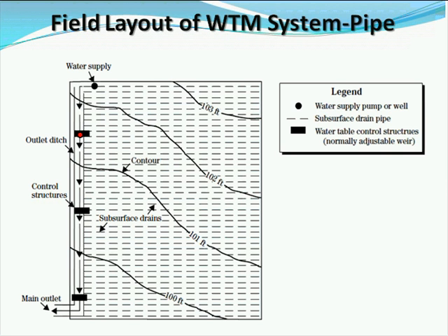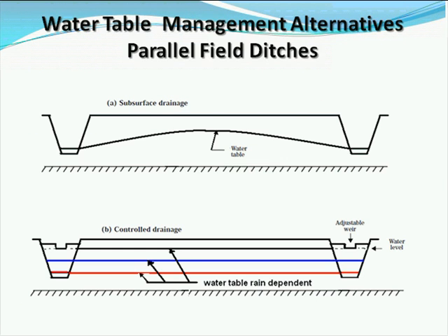and then the water level control structures would be on those ditches, and as you set your flashboards higher, it backs water up into the drainage tubing and raises the water level similar to what was shown in the earlier presentation.